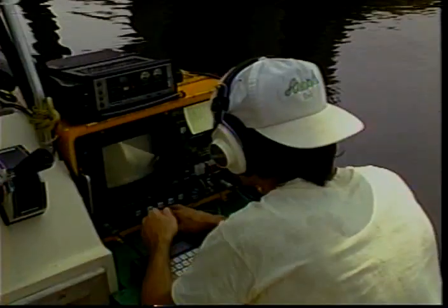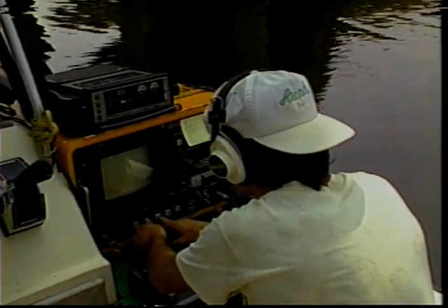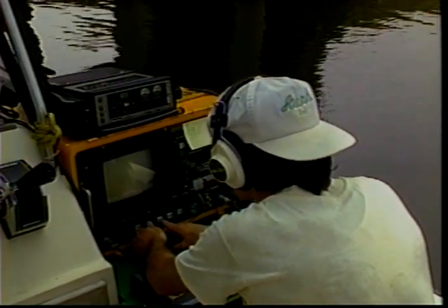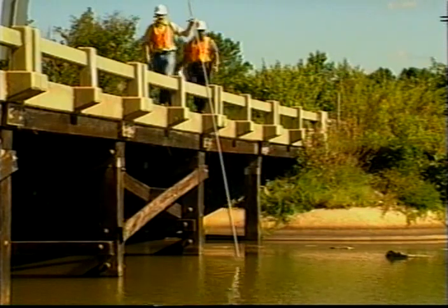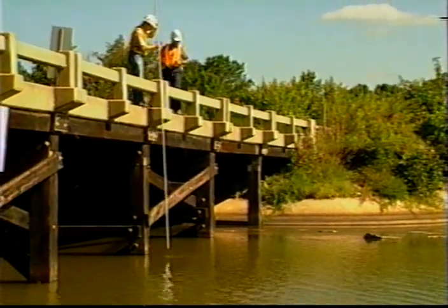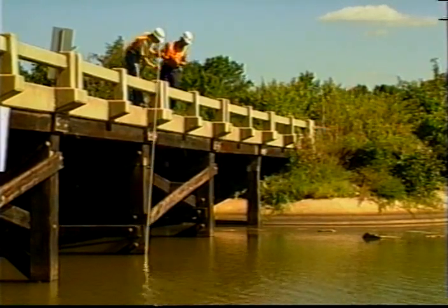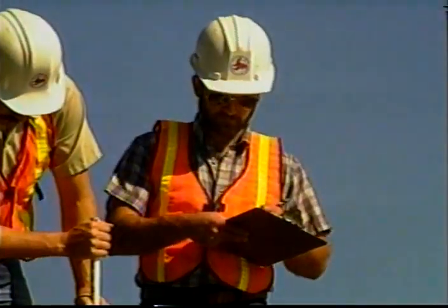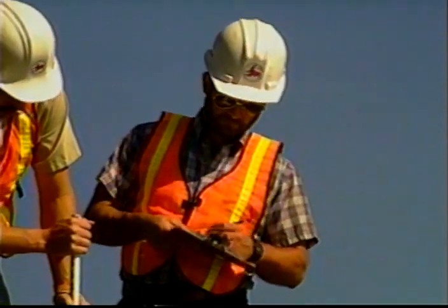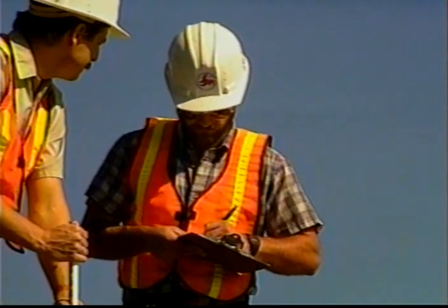For bridge elements in waterways and lakes, underwater inspection is needed. Often, video cameras are employed to make a record of conditions for later engineering evaluation. Adequate underwater inspection and monitoring the depth of the stream bed are necessary to identify underwater foundation deficiencies. Inspection results are tabulated on a structure inventory and appraisal sheet for later data entry and periodic submission to the Federal Highway Administration.